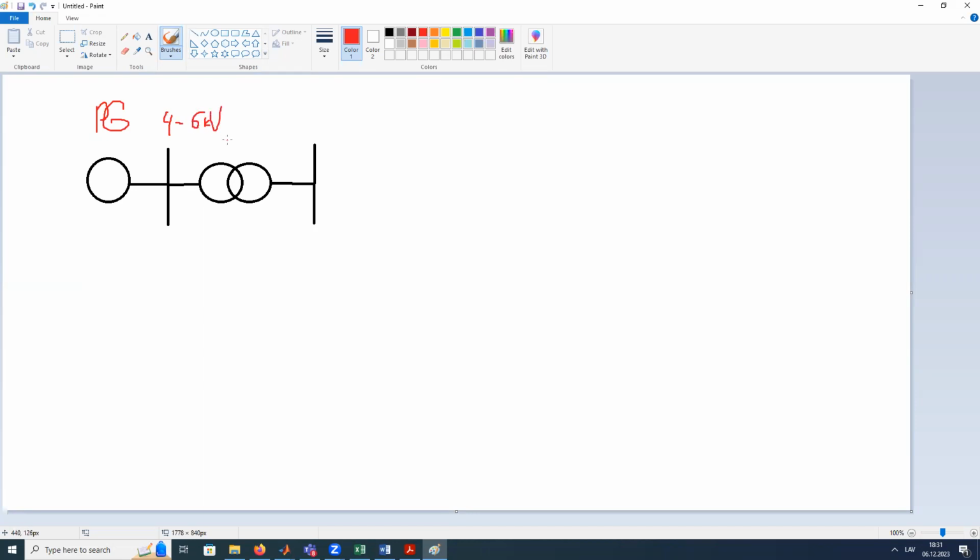Yeah, no, it's quite ordinary voltage for a power generator. I don't know what your knowledge is about electrical machines, but I think you should understand that if we have a high voltage, it means we need very good insulation. And if we have good insulation, it means we have a very huge electrical machine, a very huge device, due to all this insulation.